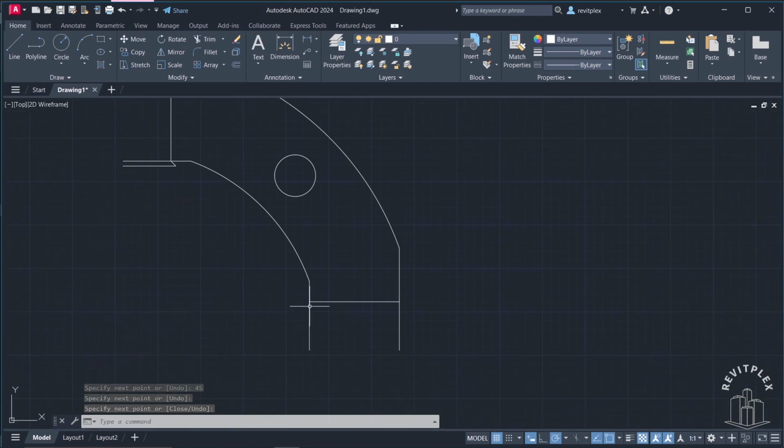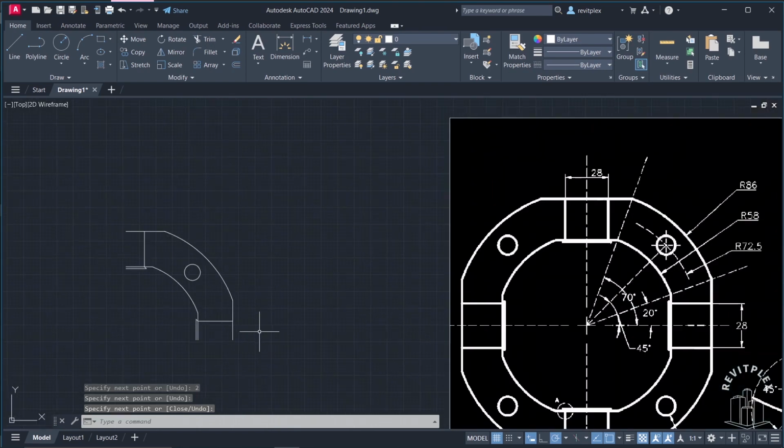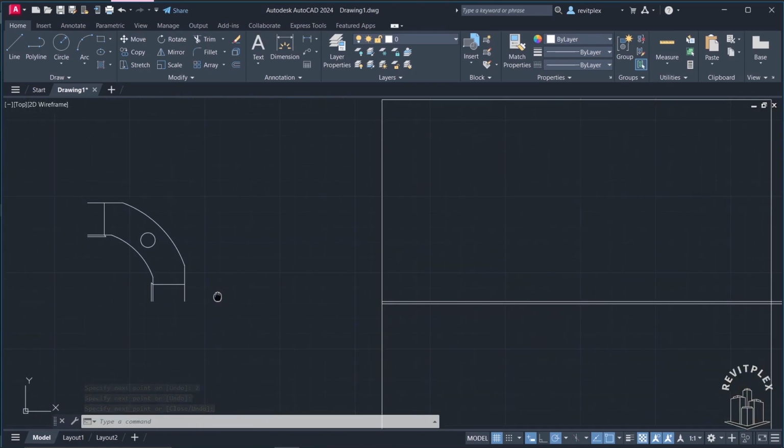Now let's move to this part. So we will do the same thing here, and I'll enter, click here, and then in this direction you have to specify the angle, and first of all let me set the angle first. So I'll set the angle at 135, press the tab key, and now I will specify the length of that, which is 2, press enter, and then just simply match it with this like this, and after that press enter. Now let's zoom out a little bit to see exactly what we have done.